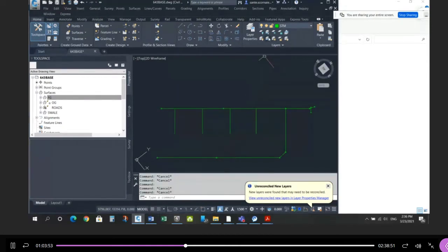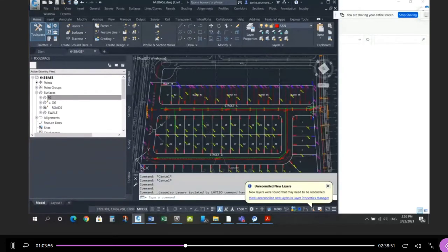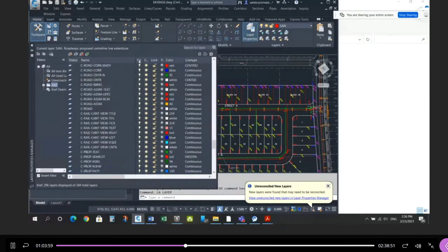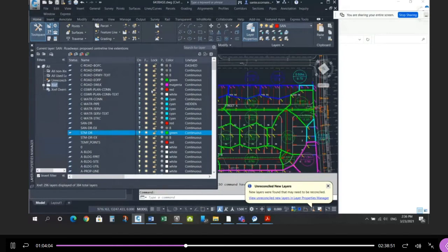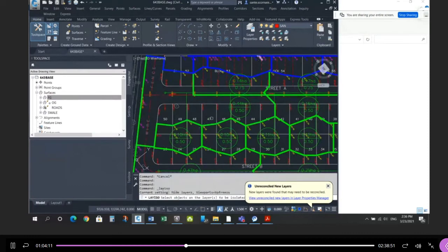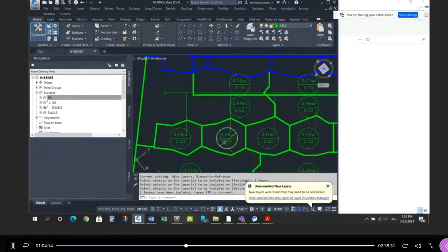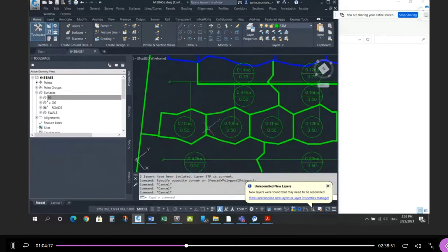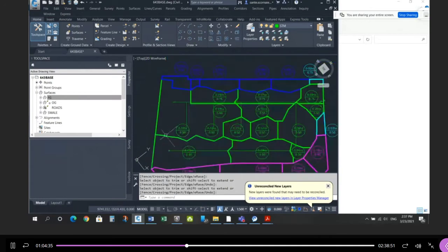And that is kind of a preview as to what I was starting to say earlier. The areas, if we bring back my drainage areas for storm, my storm drainage, what they've done in the drainage area plan that you see for the rest of the subdivision is they've combined all this. So if I look at these sewers with these drainage areas, what they would say is, okay, these two areas combine with this area. That's the total area that goes to this pipe. So then what they do is they basically eliminate these divides, right? They get rid of these. They trim this out. And now you have a total area.